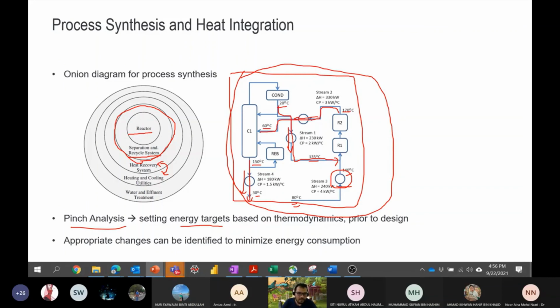In practice, we don't have such luxury because, like I said, in some streams, we don't have any flow measurements. We may not have any temperature measurements. So for that, we go back to the design case, and then we try to make a simulation using the design case. See if we can match the design, and then we can change the inputs in such a way that we can try to mimic the current operations.